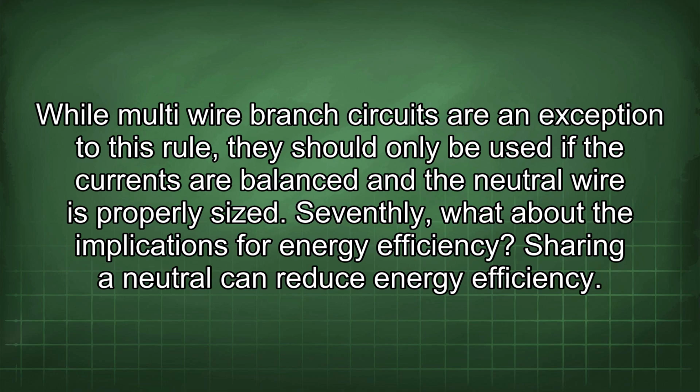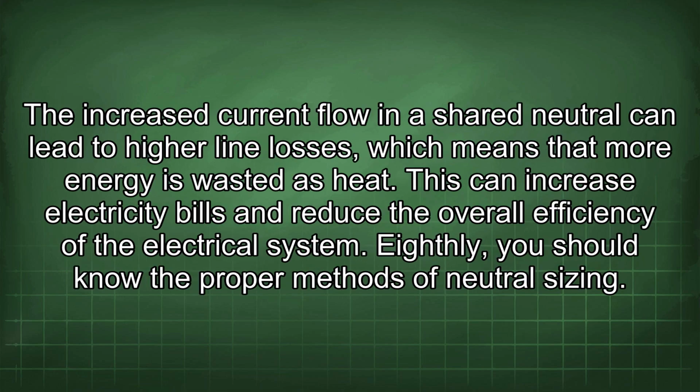Seventhly, what about the implications for energy efficiency? Sharing a neutral can reduce energy efficiency. The increased current flow in a shared neutral can lead to higher line losses, which means that more energy is wasted as heat. This can increase electricity bills and reduce the overall efficiency of the electrical system.